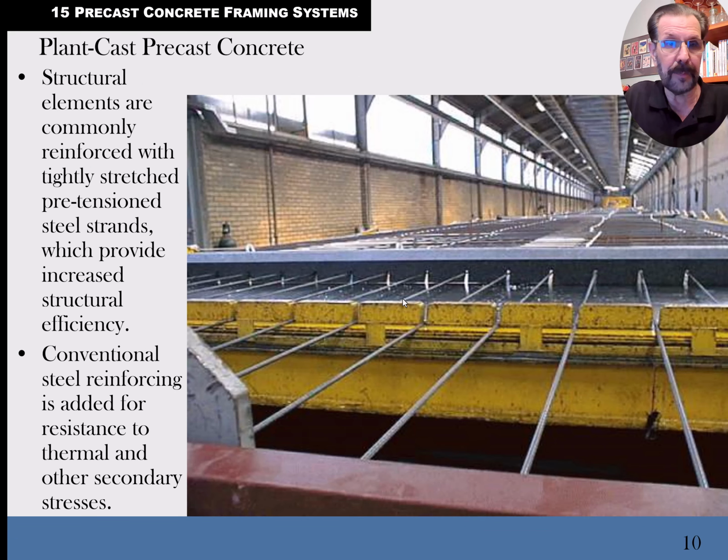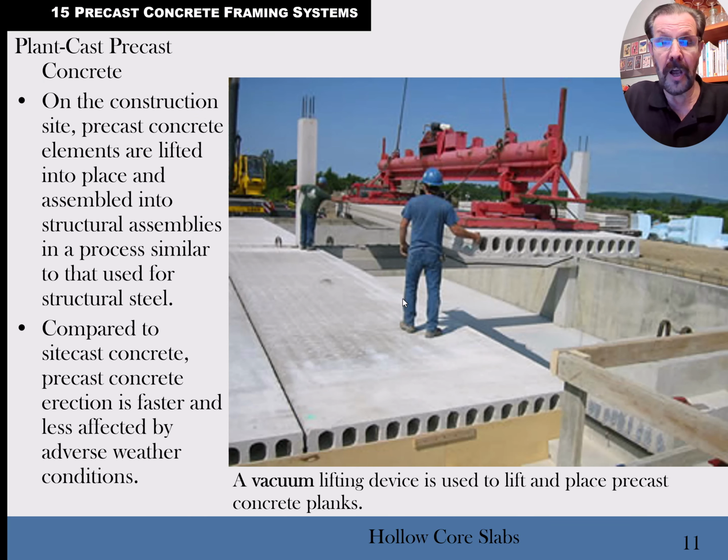Okay, and here's some more pictures of the same kind of idea with the pre-stressing strands stretched out. Here we've got the hollow core slabs that I was talking about, and there's one being picked up by a vacuum pump. They're literally a glorified suction cup system, so they can pick up this slab and place it right up against the other hollow core slab that they're standing on right now. They typically want that to be butted up right tight to it. And so that's why they need a vacuum pump.